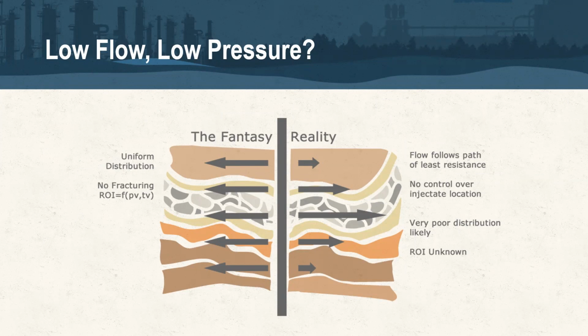I always like to pull this slide up because no matter how uniform we think our injections are and how well we've done, geology always has a different idea for us. So we need to plan for both what we know about the geology and the unexpected as well in the designs. And one of the things that we at AST love about DPT installation is DPT gives you that flexibility, right? It's not like an injection well where once you install it, that's where you have to use it. You'd have to add another well.